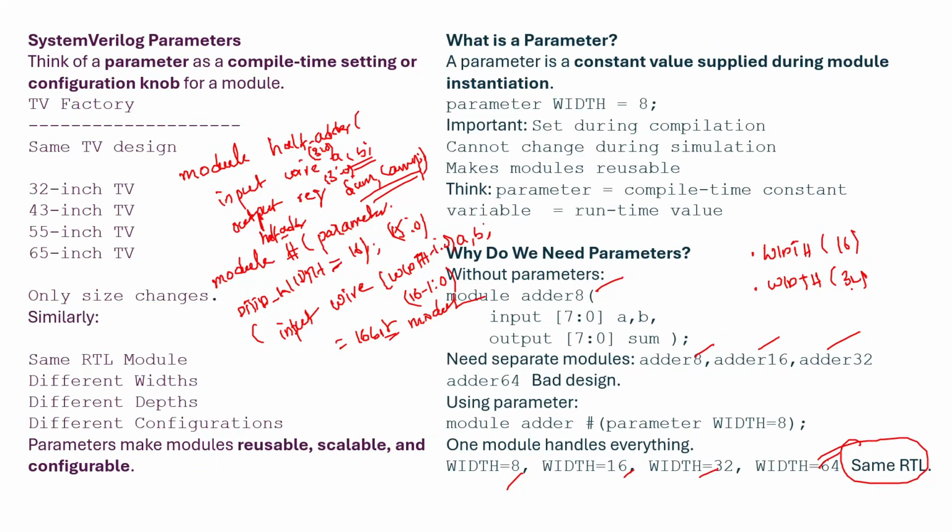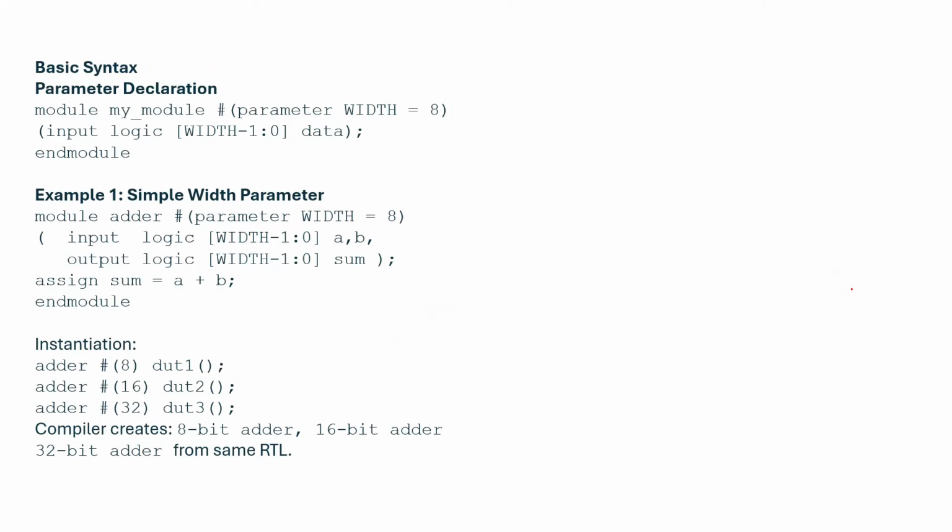Name based overriding. How we are instantiating the module in our TB, same way I can instantiate the parameter in my TB. Then we can write different parameters, so then we will go for different widths. At compilation time only we will mention the parameter width.